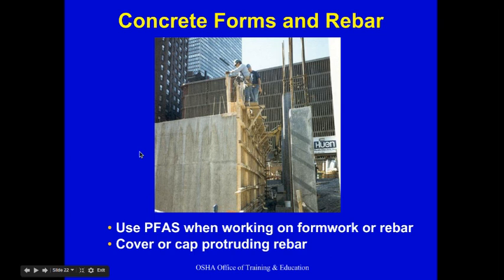Whenever you're working in concrete, these guys are doing poured in place concrete. They're building walls. You can see here, they've got one built here. They've got a wall done here, and they're working on this wall here to get it ready to pour. Anytime you're working, you're up 10 feet. I mean, these walls are 10 feet tall. So these guys are up 10 feet in the air. They don't have any fall protection. There's no guardrail. There's no fall arrest system for them. There's nothing. And the only thing we can hope is that they have a safety monitor on site.